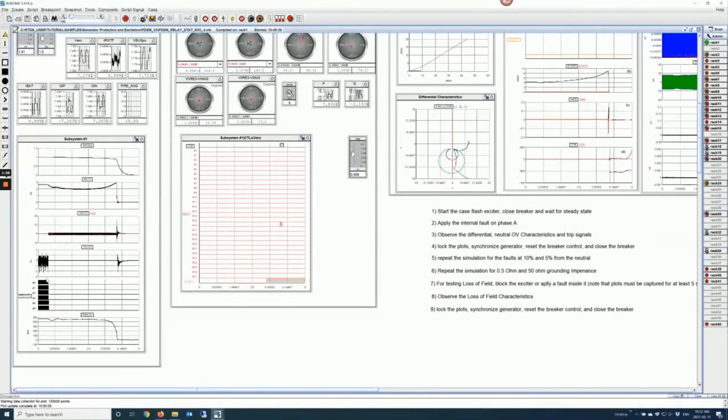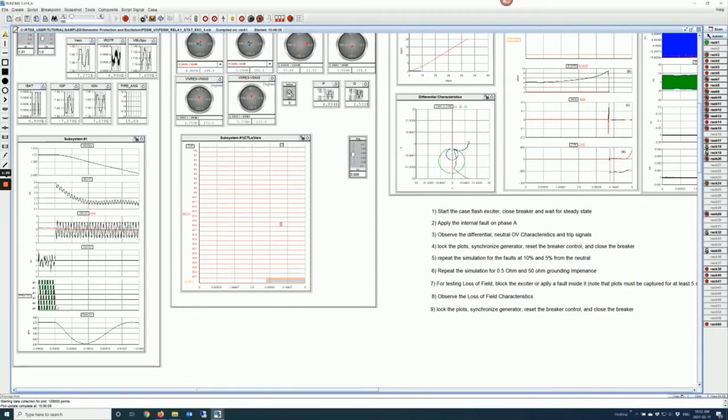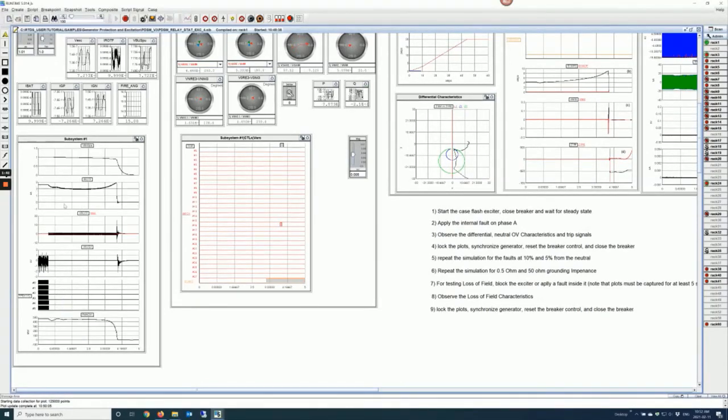Here's the time that we had our fire impulses, and right after that, we blocked them and we lost them. Our rotor field current started dropping. You see the rotor voltage, we lost the rotor voltage, but it's sort of short-circuited. It lost the field, but it pushes the current through the stator to compensate for it.